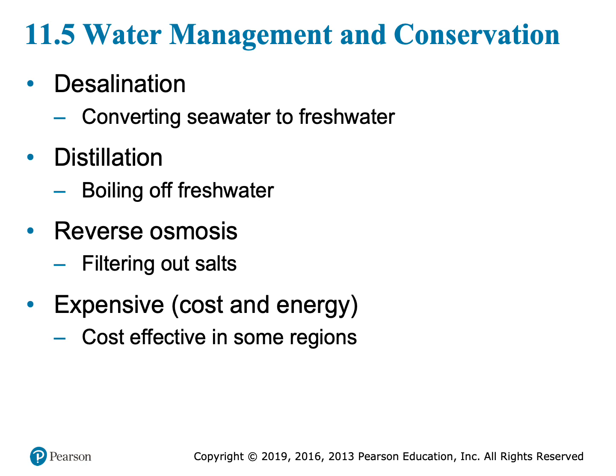So this is where we get to desalination. We're on the last page of your sheets of notes. Desalination is converting seawater to fresh water. So that's the process of removing salts and other chemicals. That's desalination. It's extremely expensive. The two main methods of desalination are distillation, which is boiling water and condensing the steam, and reverse osmosis, which is filtering water through a selective membrane.